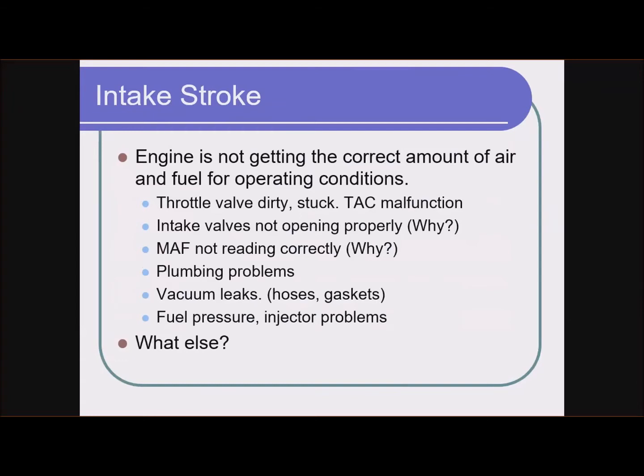Mass airflow sensor not reading correctly. That's an intake stroke problem. That's really going to screw up the computer's calculations on fuel delivery. What can go wrong with a mass airflow sensor? Well, the sensor itself can go bad, obviously. Sensor can be unplugged, wiring problems to it.